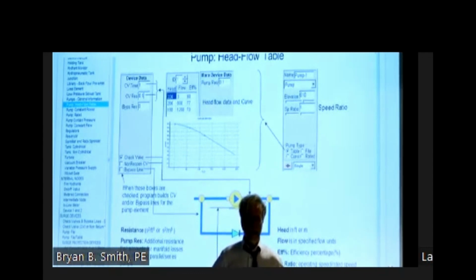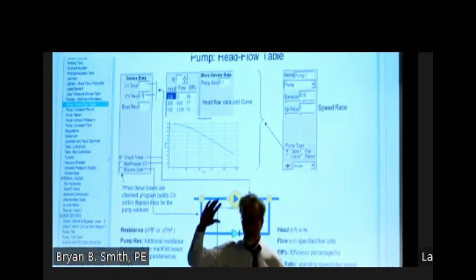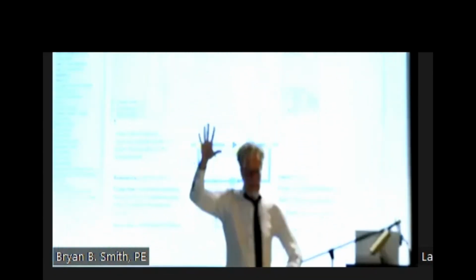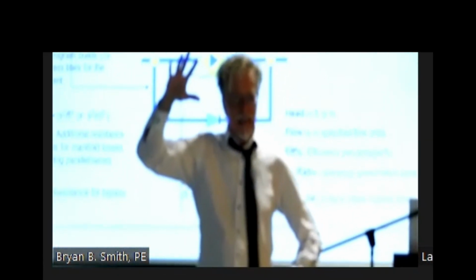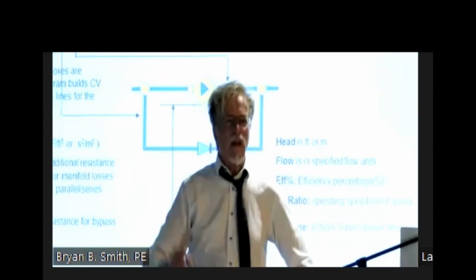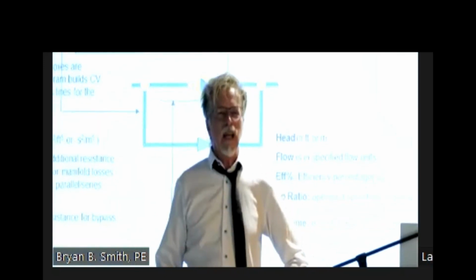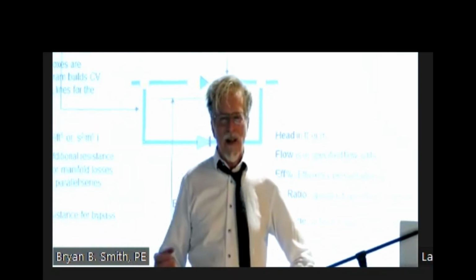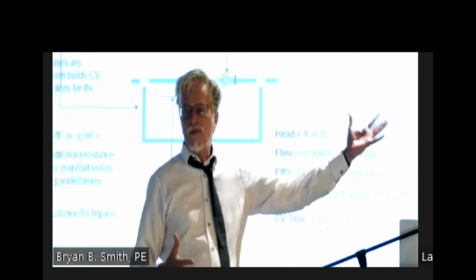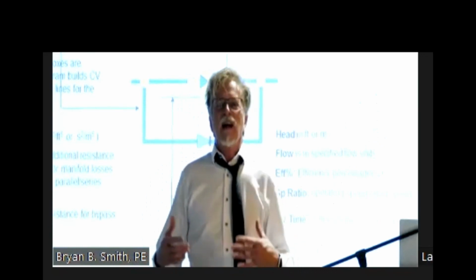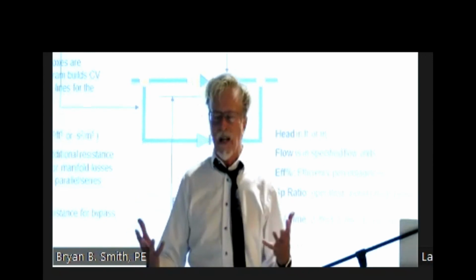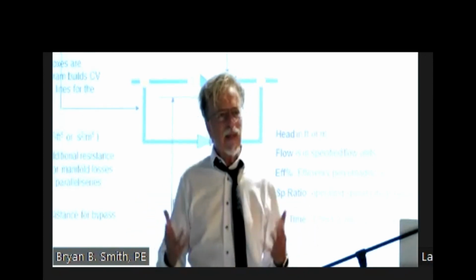I had a project in Brazil, and in this apartment complex, everybody had their own storage tank and a flow path. They had horrible pressure transients in this building that were destroying it from leaks. We also see that in cooling towers, with the makeup water valve. That valve is critical, and it can create huge pressure transients, which show up at 400 or 500 psi. So control valves matter. Slow down if possible. If you can't slow it down, put in a surge vessel or a damper. Accept that energy.